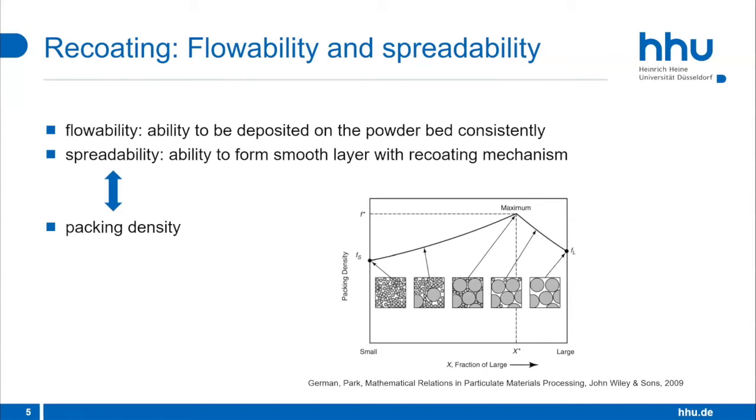So Lena, you also asked the question before what the desired particle size is, and Johanna mentioned before that the target value should be around 50 micrometers, and the same is true for the standard commercial material. So it's polyamide with 12 carbon atoms, and there the X50 is usually around 60 micrometers, maybe 70 micrometers. It has a comparably sharp particle size distribution.